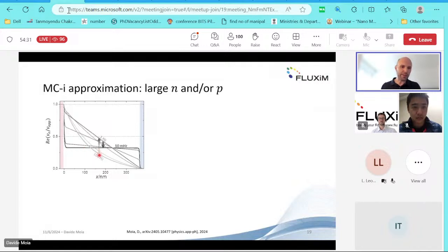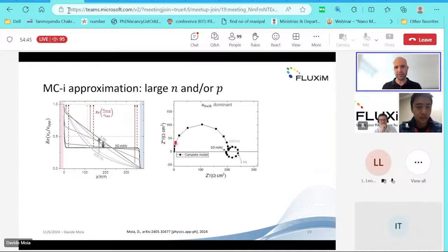So this essentially means that we have two regimes, two different polarization processes at low frequency. And indeed, this will provide two transitions for the dominant recombination driving force. And this is reflected in the impedance that we calculate for this system in one and two changes in the low frequency recombination current and therefore recombination impedance.